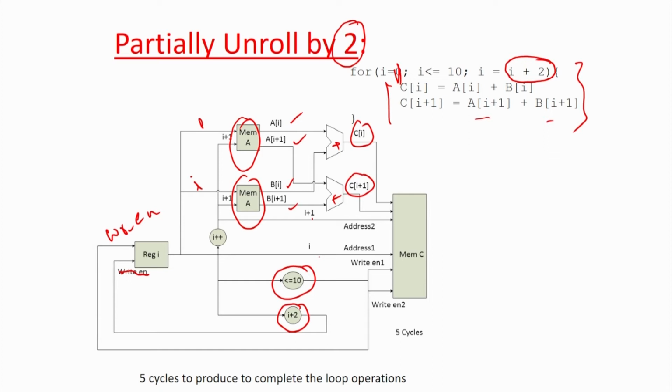So, this is kind of a trade off between fully unrolled versus fully pipelined, because now I need 5 cycles to complete, because the loop is iterating for 5 cycles. I am doing the operation of 2 iterations at the same time. So, this is a trade off between partial unrolling, fully unrolling and pipeline, and which is your good choice depends on your requirement.